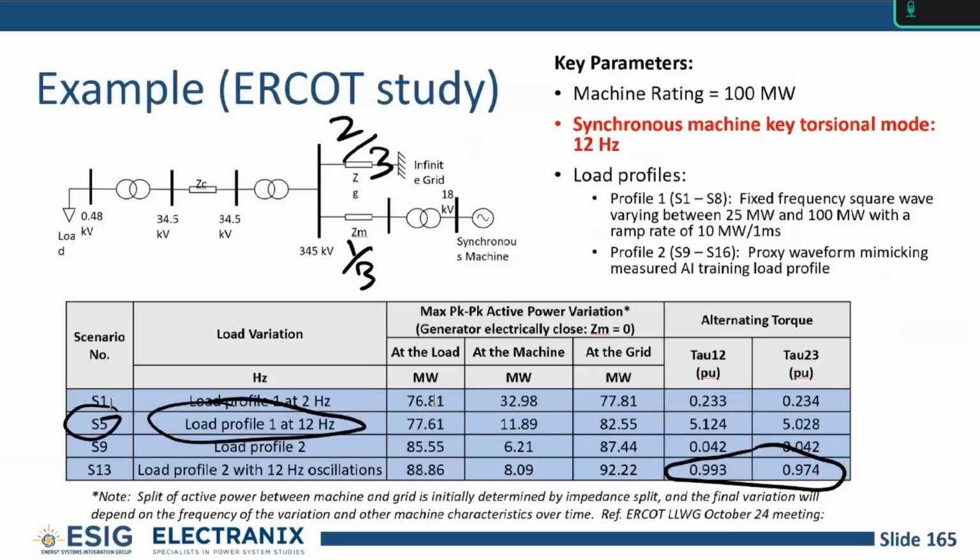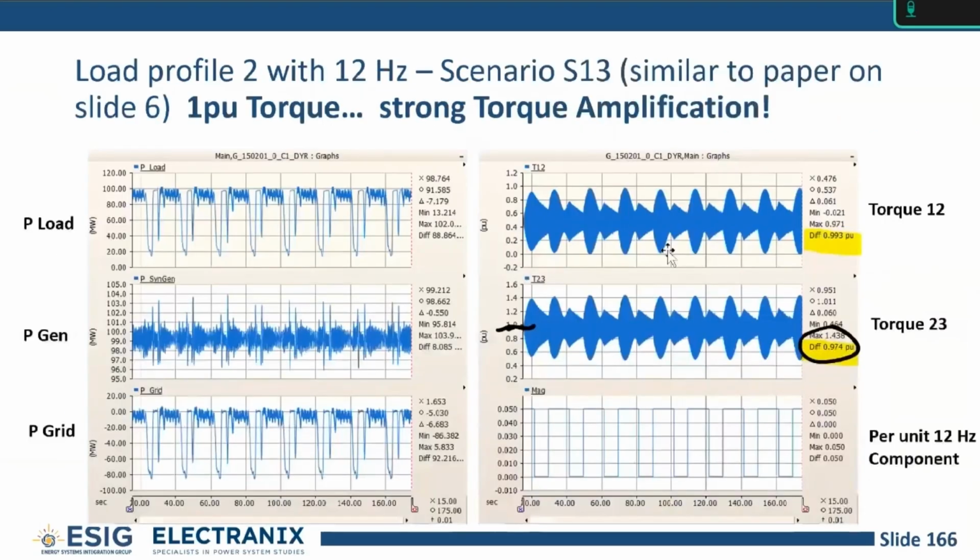But even the one that is a little bit more likely, this recorded value, if you add some subsynchronous portion on the top, you have a chance to fatigue the shaft. And if it's not 5 per unit, but it's 0.5 per unit, now you're into the fatigue region of that SN curve. You won't see a failure right away. You'll see it after a certain number of cycles. So you might start to see generators failing early rather than failing immediately.